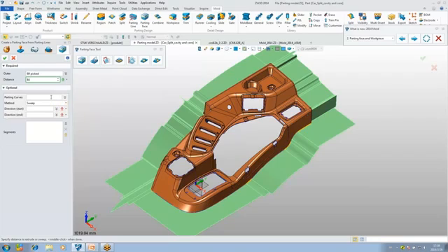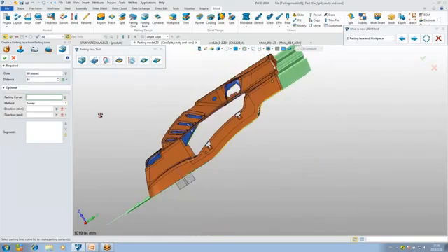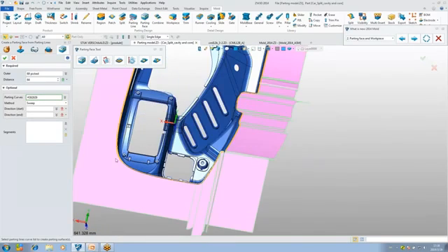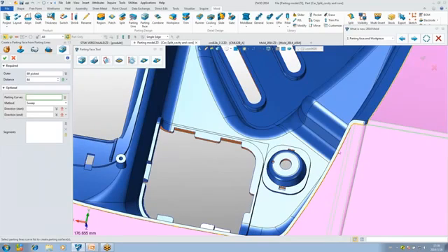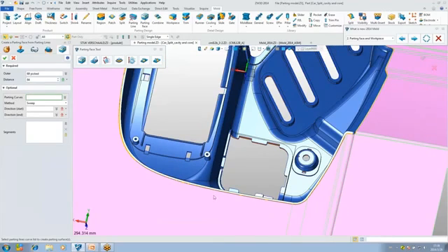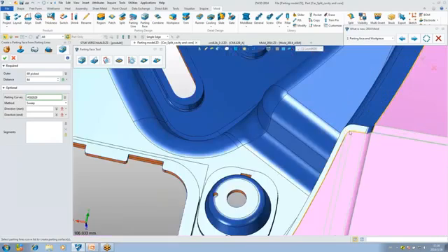For the new version, ZW3D supports defining different pattern faces using different methods to generate the pattern face. For example, for this face, actually this plate is one plate, but it generated several pattern faces here, so it's not so clear. Here we will select it: 1, 2, 3, 4, 5. Select all the edges from this plate face.